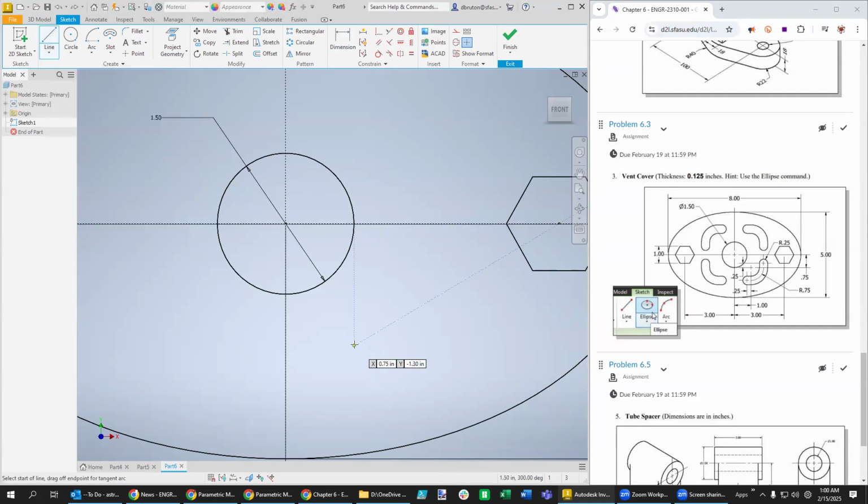a line that makes that L shape, like so. That needs to be vertical. Okay, let's see, vertical. And this one should be horizontal here. Looks like it already is. Okay, so what needs to happen here is that this radius of curvature in here, before we start to make this wrap around the outside, this middle has to have a radius of curvature of 0.75. So we get out the fillet tool and we say we want that one right there to have a radius of 0.75. Now it's not properly placed in space, so we need to get that working.